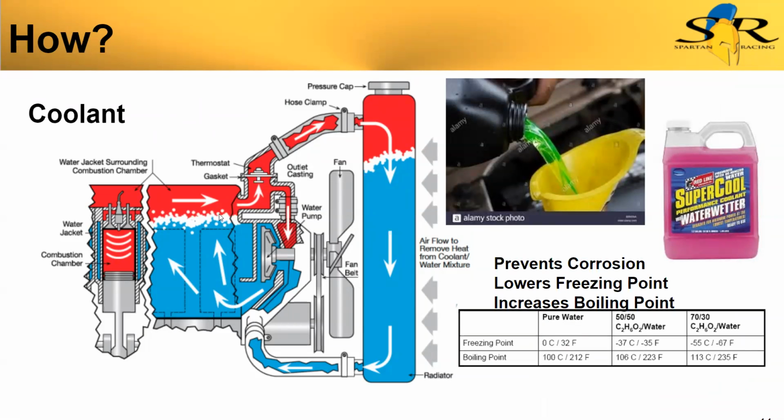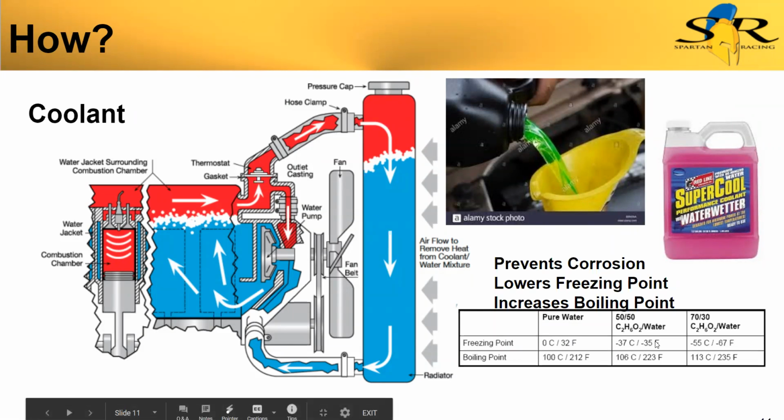And I already talked about coolant some. Typically, your coolant is going to be a mixture of water and ethylene glycol or propylene glycol. And that's this green or sometimes orange fluid, different colors, with that sweet taste that cats love. It is poisonous, so don't drink it. Don't let your cats drink it. But here's a chart that kind of talks about the different ratios and how that affects the freezing point and boiling point.